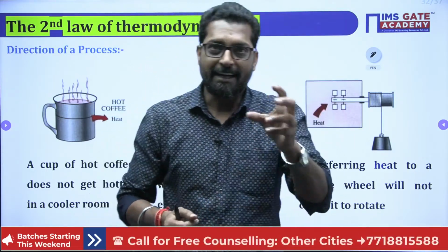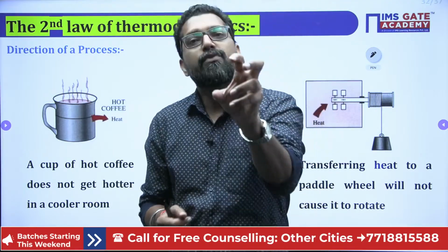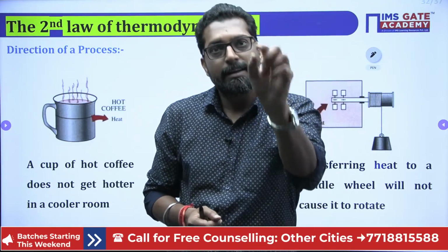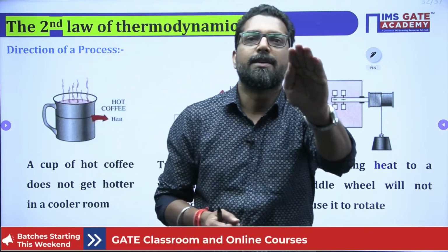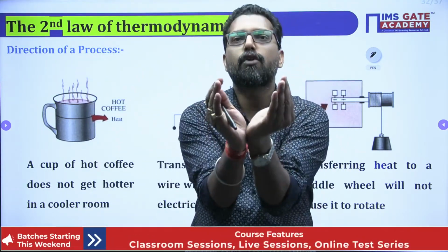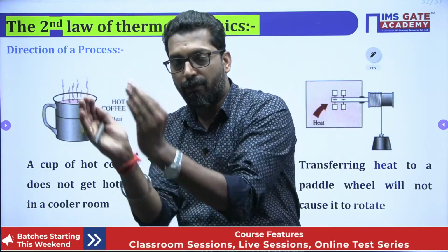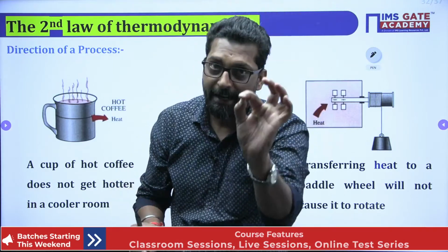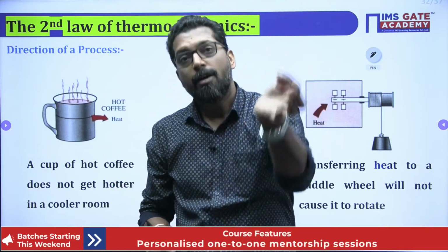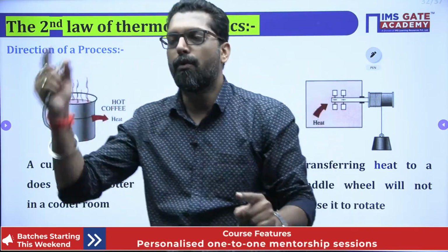For a non-flowing system, internal energy plus kinetic energy plus potential energy per unit mass is the stored energy. When the fluid is flowing, the stored energy is internal energy, kinetic energy, potential energy plus flow work.